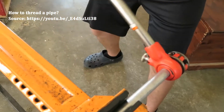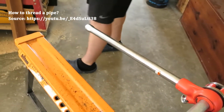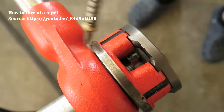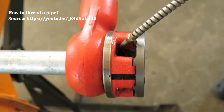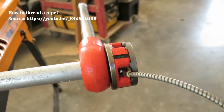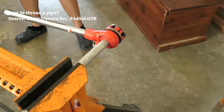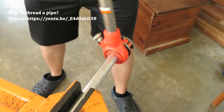Now, before he gets going too far, he's going to oil this. It's biting now, and you know these cutters do a lot of work, so they need to be lubricated. This is special cutting oil. It's got sulfur in it, which lubricates the cut as it's happening. So there you go.